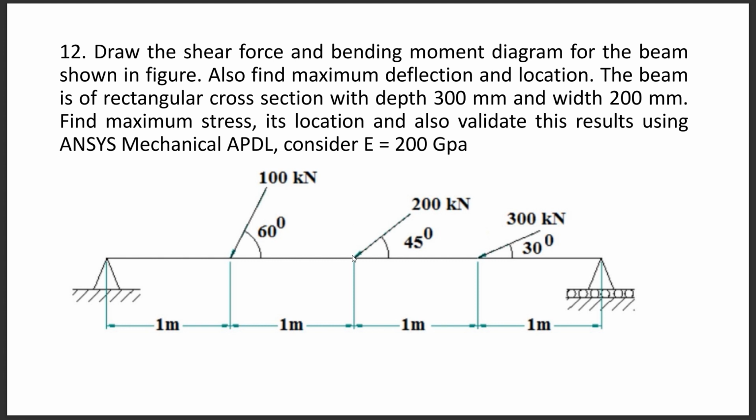So to have this kind of orientation, we need to rotate this point in the clockwise direction by 45 degrees. Similarly, for the third one, if we are not rotating, normally the angle should be 90 degrees. Now to have an orientation of 30 degrees, we need to rotate the key point or node by an angle of 60 degrees in the clockwise direction, so it will be minus.